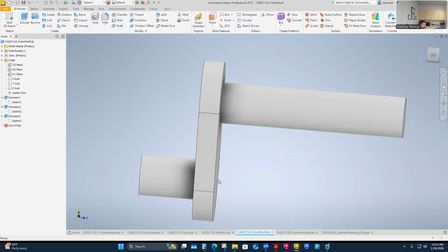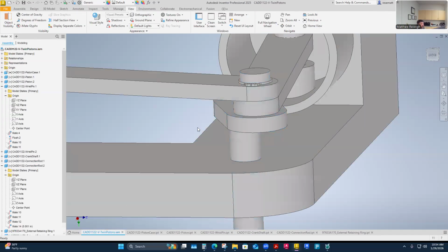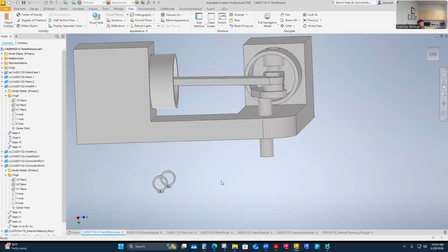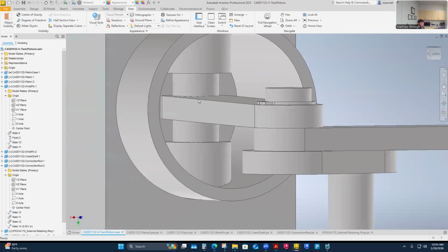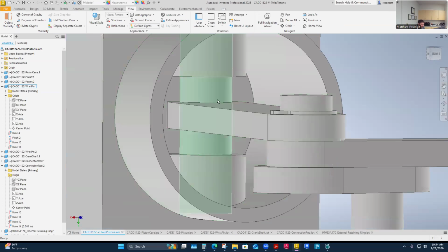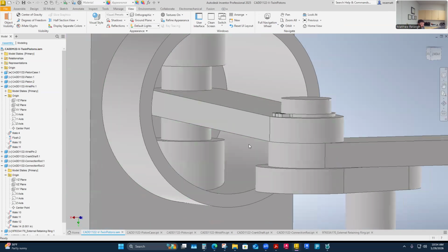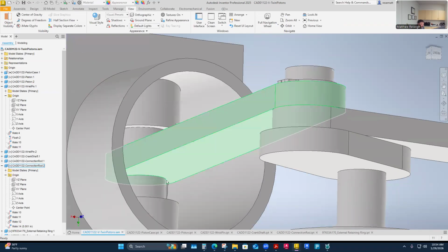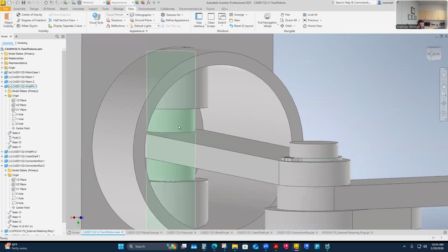I know for sure that's where I want to use these particular fasteners, in this easy to get to open environment here. But then the other thing I'm going to do is come in and place those other fasteners that are the snap-on style. And then I'm going to place those with the minimum tolerance away from this, probably 0.008 away from this face and 0.008 away from this face. Then I've got to go into that part and cut the groove to fit that particular part.